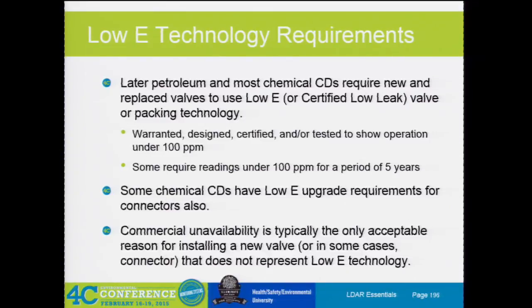Some of the newer chemical CDs have requirements also for connectors. So with the chemical side, a lot of you folks do HON or MON-based regulations, and so you have connector monitoring requirements. And so they've also added in low E connector pieces. So, you know, changing out your gaskets and using a different type, and there's certain companies out there that actually will make that and give the certification.